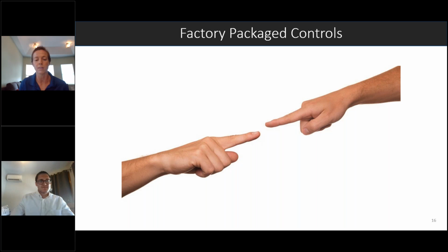And then you can leverage the other USB port to plug in an EnOcean transmitter to pick up wireless devices over EnOcean, or even Bluetooth is a third option. Or you can use a USB port to, as we were joking, charge your phone. So whatever. Or add extra memory and storage. Yeah, there are definitely quite a few ways of doing it. Wi-Fi, EnOcean, and Bluetooth are what Distech has within their offerings.